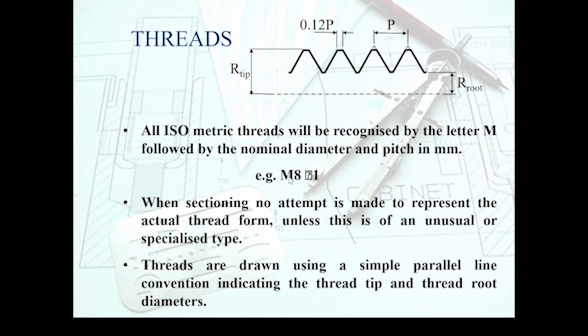Now in the UK we generally follow a metric system where something like M8 actually means a nominal diameter of 8 millimeter, and M stands for metric, and there is only one thread type. So if you were to go to any of the DIY stores, you'll be able to quite easily buy the fasteners if you were to follow this regulation here, this guideline here.